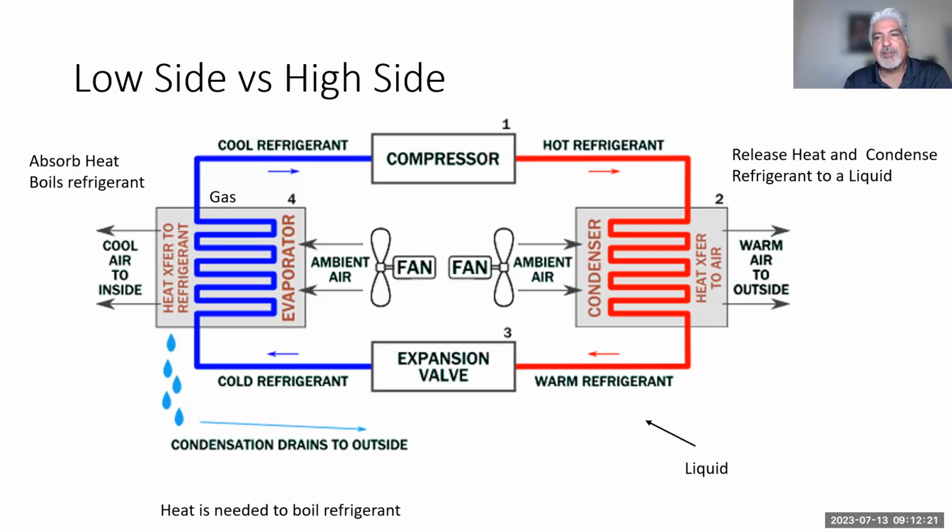Now, the big thing you have to understand, as I get into the compressor side of things here, is that the compressor does not like liquid. It will hydrostatically lock it. So if you want to destroy a compressor real quick, have it see a liquid. It should not see a liquid on the suction side. We'll get more into it. I don't want to jump ahead so fast. But yes, the compressor needs to see vapor.